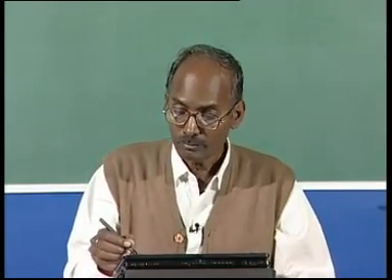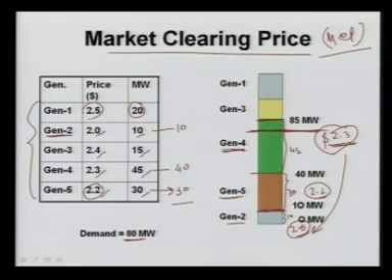Also here, some people are very risky, they are continuously operating, so they can bid, they don't know the market. Here if you are going to pay as bid, what will happen? This generating company will try to see what the market clearing price will be, and it will try to bid more than that. Let's suppose earlier it was bidding at 2, now it thinks the price will be 2.3 or 2.4, let's suppose 2.4. What will happen? Now you can see this generator coming up, and then the market clearing price will be increased to this one, because this will be the deciding factor.